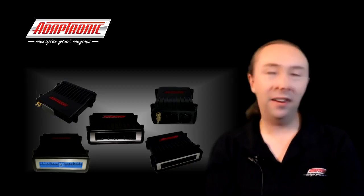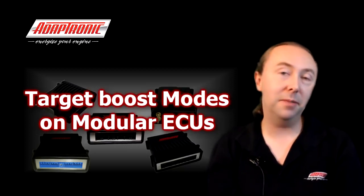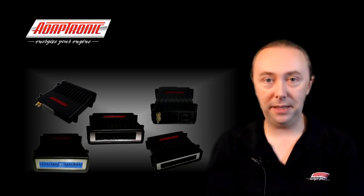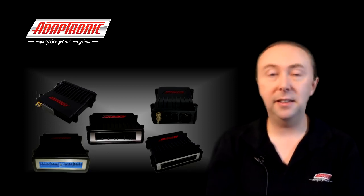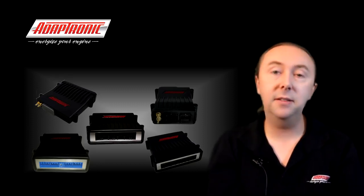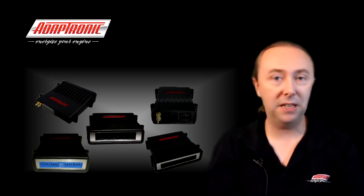Hi everyone, in this video I'm going to talk about using target boost modes with modular ECUs. So first of all, let's talk about the reason why we do it this way. What we found with the select ECUs was that the majority of people were happy just to run an open loop boost control system where you just specify the duty cycle and that's about it.